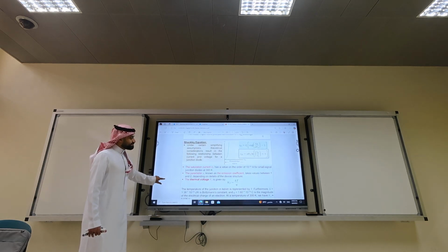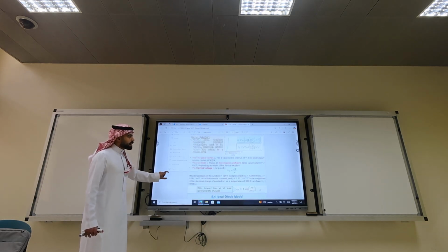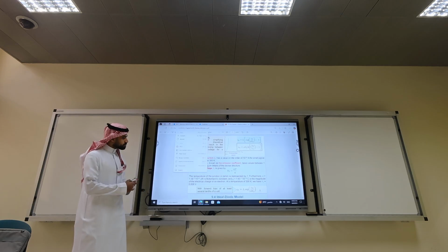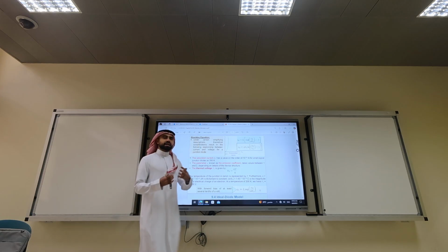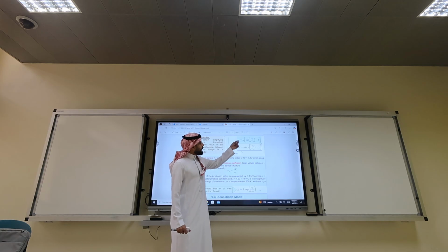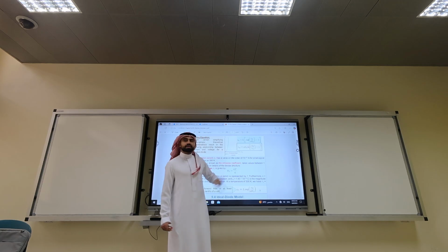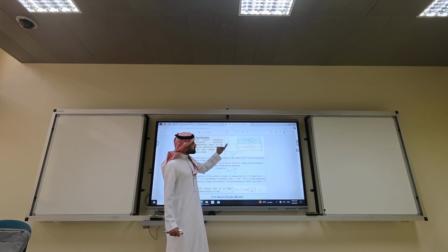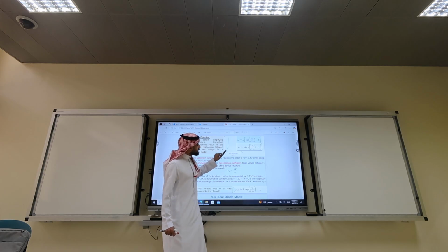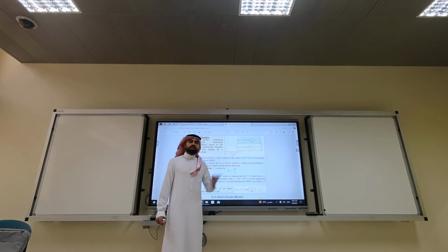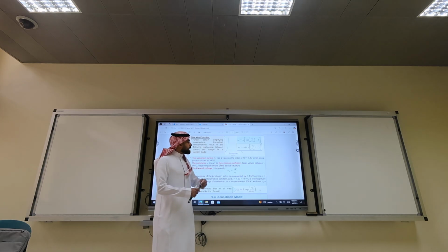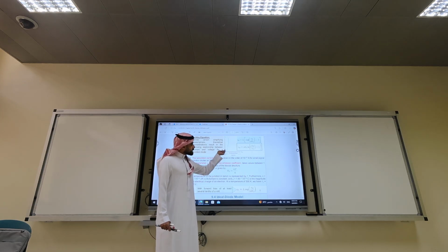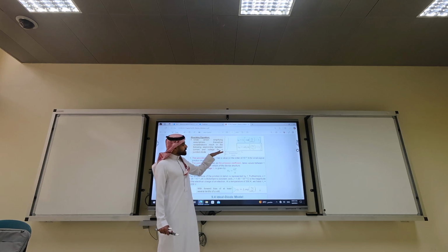Today we will talk about a very simple equation, though I do not think it's very important. We call it the Shockley equation. The Shockley equation basically explains the relationship between ID and VD in the forward bias region. So do you see, this looks like what? Exponential, right? Just above 0.7 volt, the current increases exponentially. Depending on where you connect the diode, it could be 2 milliamp, it could be 5 milliamp, but what matters to us is as long as there is enough voltage, some current will flow.